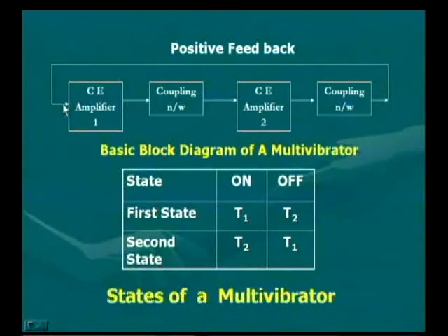That means it will be in phase with the input signal. Hence the feedback here will be positive feedback. And one more thing here is the feedback signal amplitude will be so large that the transistors in these circuits can be switched from on to off states or off to on states instantaneously. That means the amount of feedback is very large so that the transition can occur within no time.